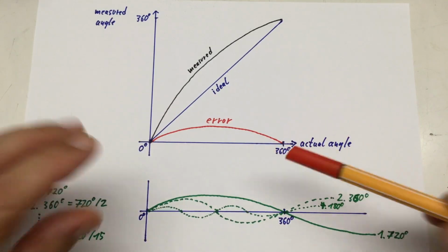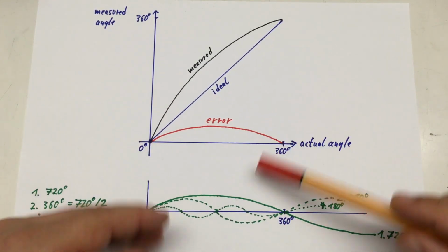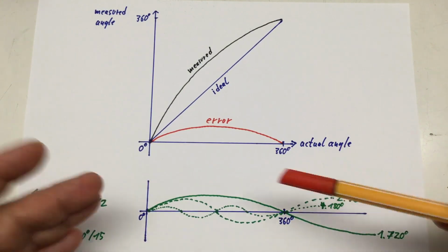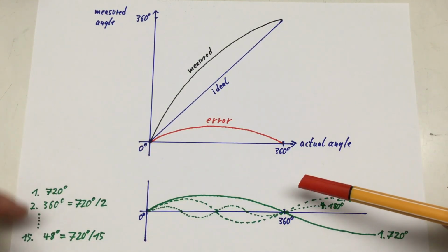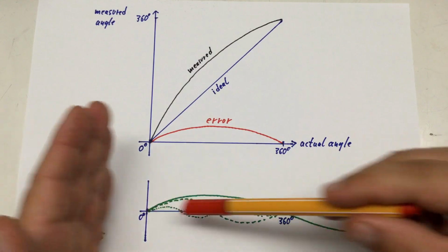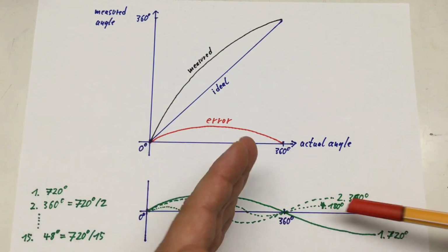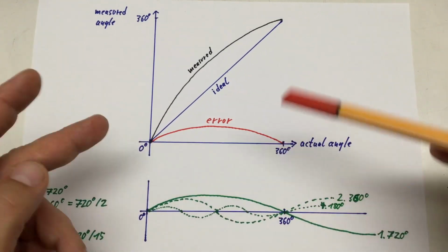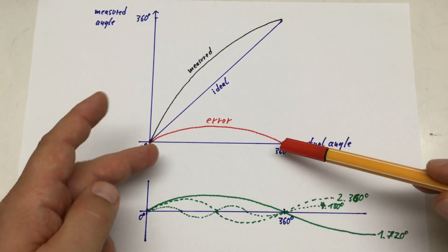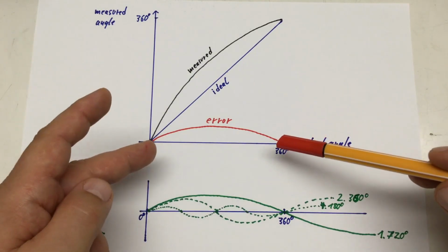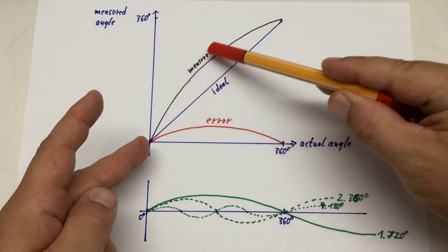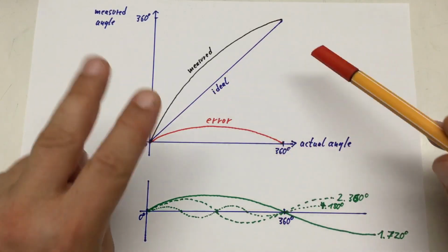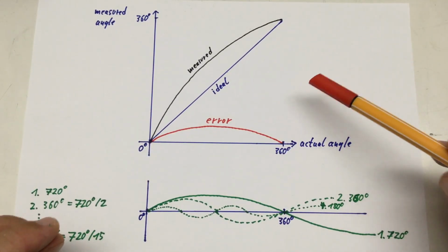After you stored all this in the SRAM, the A1335 can use that information to simply add up all your 15 wavelengths, probably shifted by the phase and multiplied by the amplitude, to get to an error curve, which it then subtracts from the measured values to get to our ideal linearized curve.